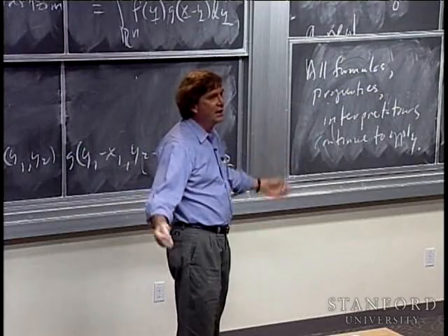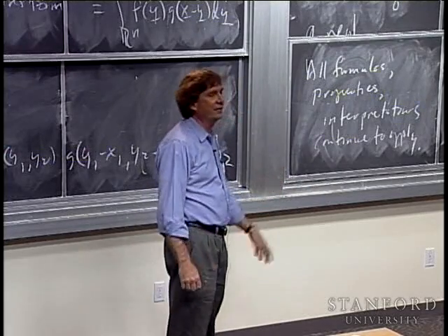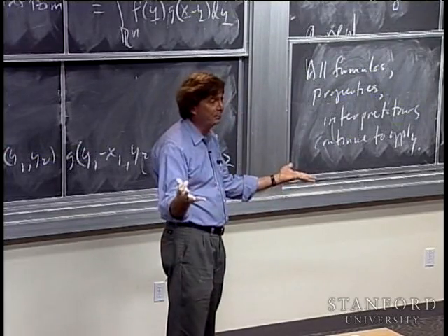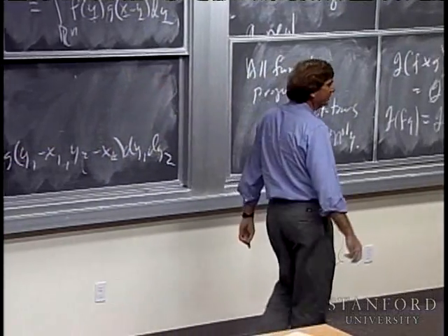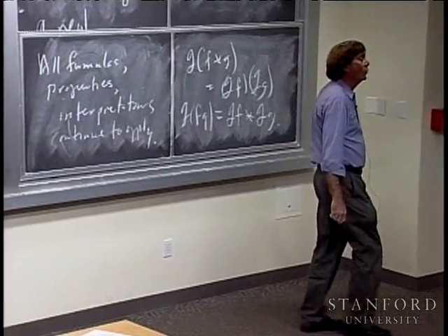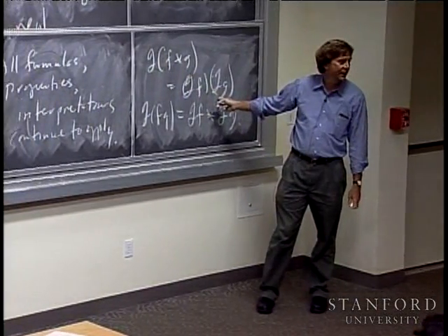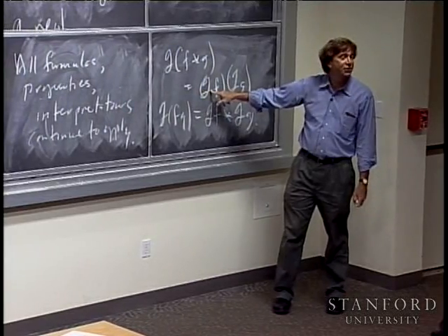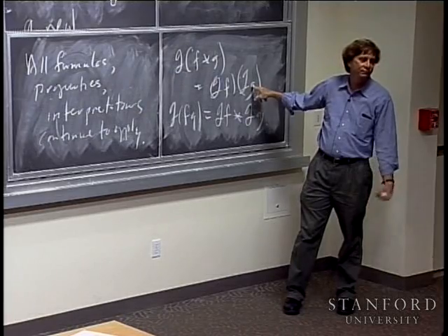What is an image? You can think of an image as a function of two variables, x1, x2, where the value f(x1, x2) corresponds to the intensity. Think about black and white images, going from 0 to 1. How do you do filtering? How do you do signal processing on images? Well, most often you do it by some sort of multiplication in the frequency domain: the spectrum of the image times some mask, some filter that you are cooking up.